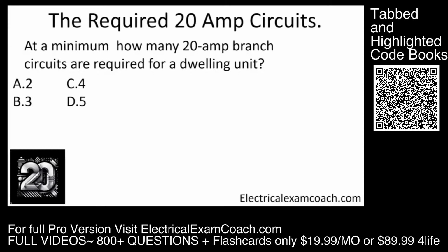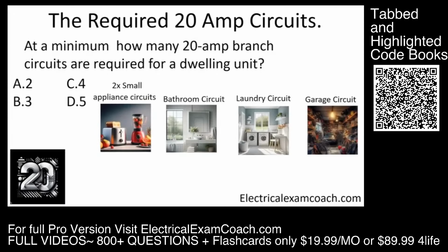At a minimum, how many 20 amp branch circuits are required for a dwelling unit? Now, this is asking a very specific question. There is a code minimum of 20 amp branch circuits that are required in every dwelling unit. The correct answer to this is 5. It's going to include our 2 small appliance circuits, our bathroom circuit, our laundry circuit, and our garage circuit.